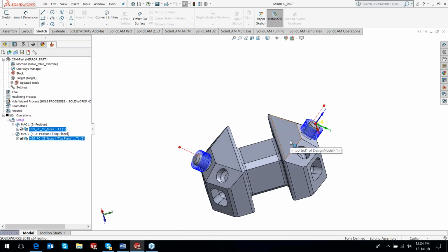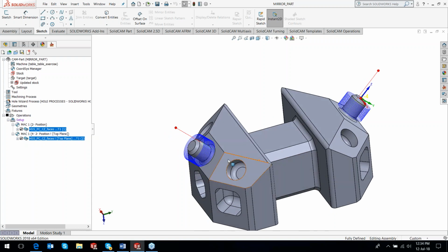Now the best part about this mirror toolpath is that this is going to be our unique feature. There are some, but they don't work properly. But here it's going to be a pretty unique feature, that I can keep the machining direction the same as my original toolpath. So if I used climb in my original operation, I can keep climb in my mirrored operation. I don't change the direction of machining.